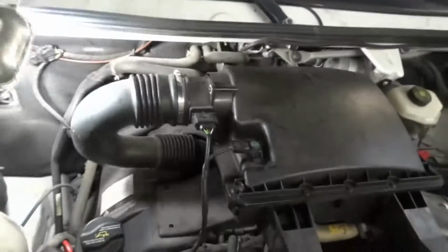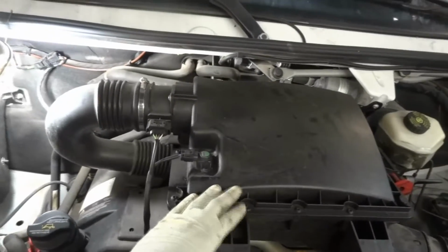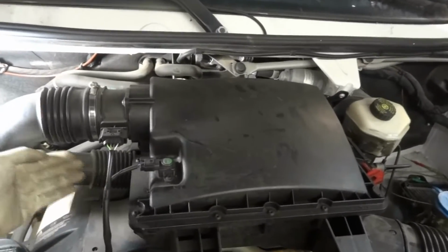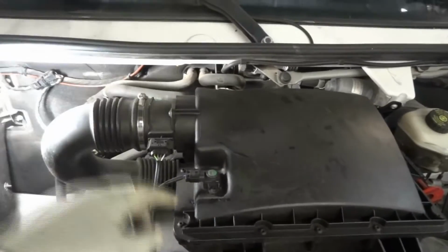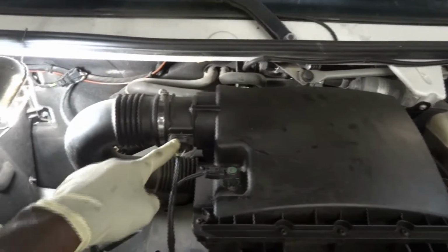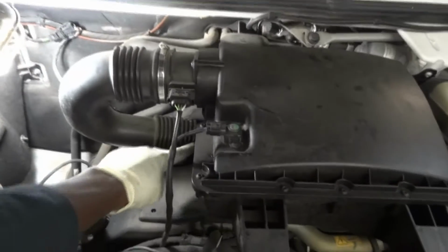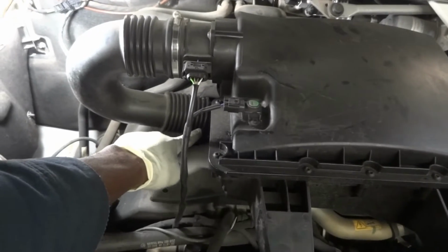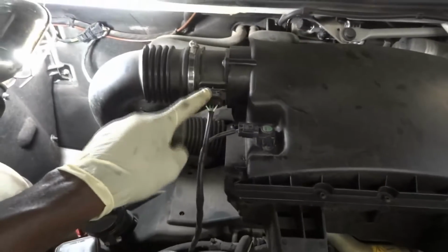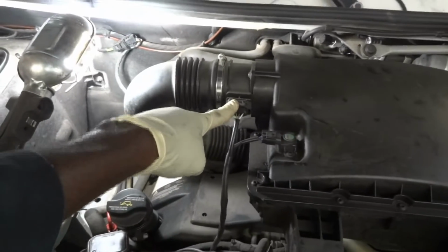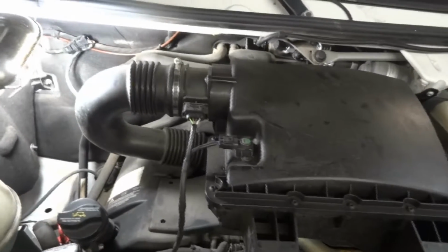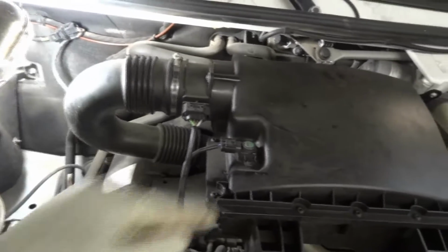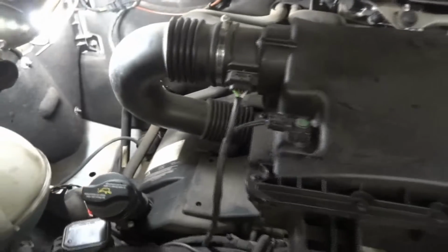And if we have a leak there, all the air that's coming from the air filter can be leaking out of there, or it can be drawing more air from that gasket. Because the computer is looking at the input from this sensor, if we have a leak on that gasket that I showed you down there, it's gonna skew the reading that's coming from this mass airflow sensor. So the computer is not gonna know. And remember, on that code, one of the possible causes was an air leak on the intake.